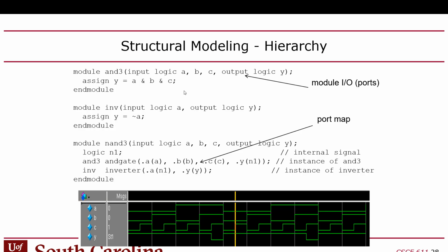Okay, so once you have that set up, then you could simulate this, and you would typically show it on a waveform editor like this. You can see that A, B, and C are being toggled. Now this is a little misleading because A, B, and C are being driven by an unknown force here. In reality, I use Tickle commands. The simulator has a scripting interface called Tickle. Tickle is TCL, which stands for Tool Command Language. A lot of CAD tools use Tickle for interacting with them.